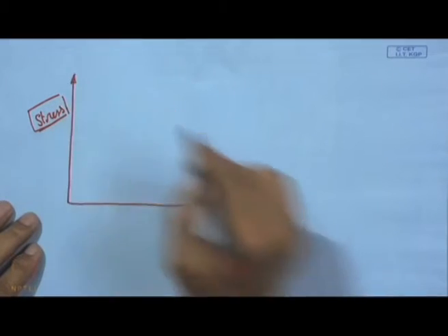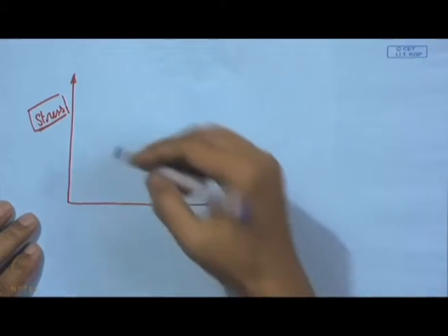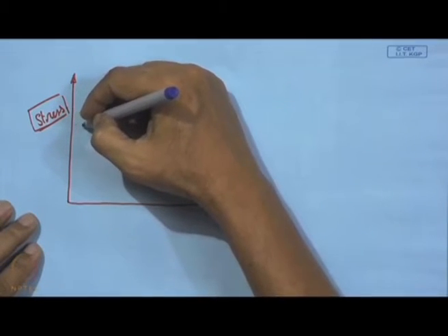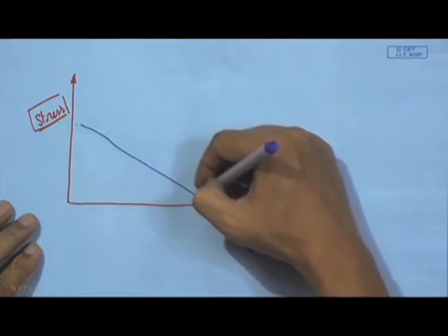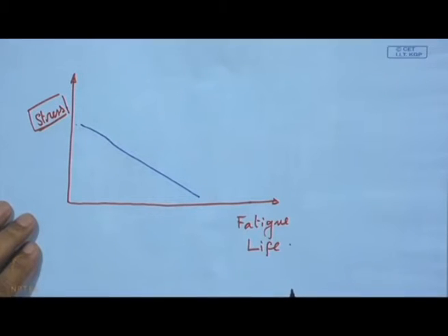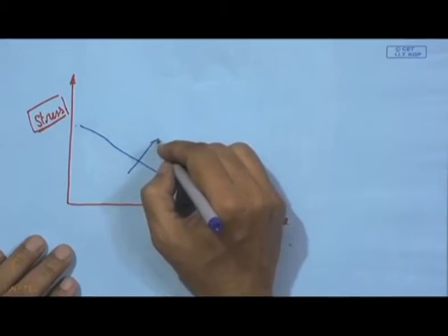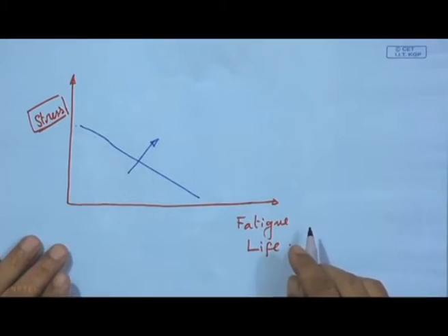So, in proper scale log-log plot, just to give an impression of what we can do, we can get a series of curves more or less following this nature. Okay. So, these are the curves. Now, what is our objective? Why do we do all sort of this mechanical working, whether it is shot peening, roll burnishing or ball burnishing? The whole idea here is to shift this curve in this direction. In one sentence we can say that this is our sole objective.